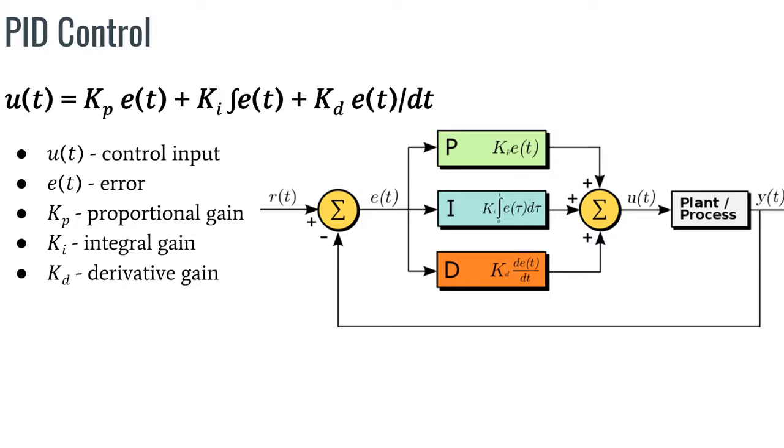So when we think about feedback control systems, we said PID control is one of the important ways we can build feedback control systems. We identified that it is a three-part controller. It has three main components: a proportional component, an integral component, and a derivative component. We will briefly look at what each of these means and why we use these within our controllers.